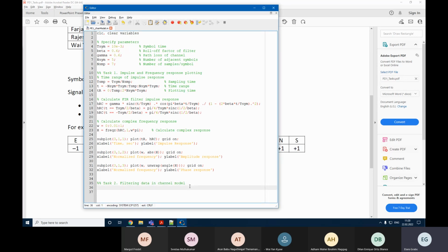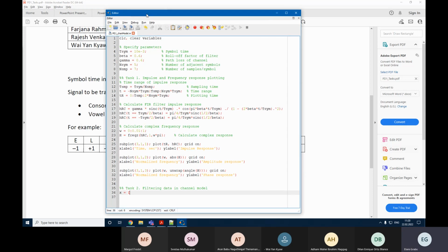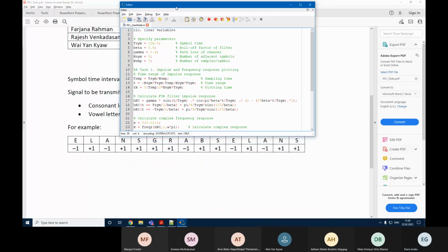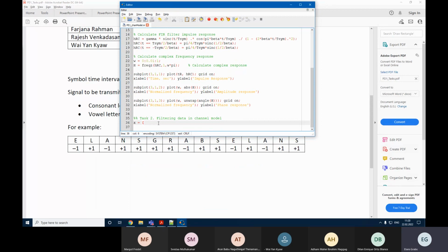So what we need to do here is first specify our signal. We will specify it as x. I'm going to make this a little bit larger to see and type at the same time. Just by separating with commas, I am specifying this array manually, as a row vector. +1, I have it 4 times. -1, +1, and I repeat this until I get 15 symbols.